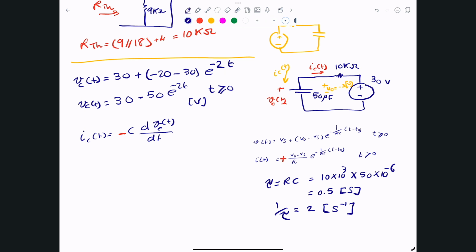Anyhow, either of the solutions is fine. I'll just use the equation because the equation is based on this one here, so I'll just go ahead and compute it. So what I'll have is the following. We have V0, which is -20, minus VS, which is 30, divided by R, which is 10. I can keep it in kilo ohms, so that the result, volt divided by kilo ohm, will be in milliamps, e to the -2t, and that will become exactly -5 e to the -2t milliamps,